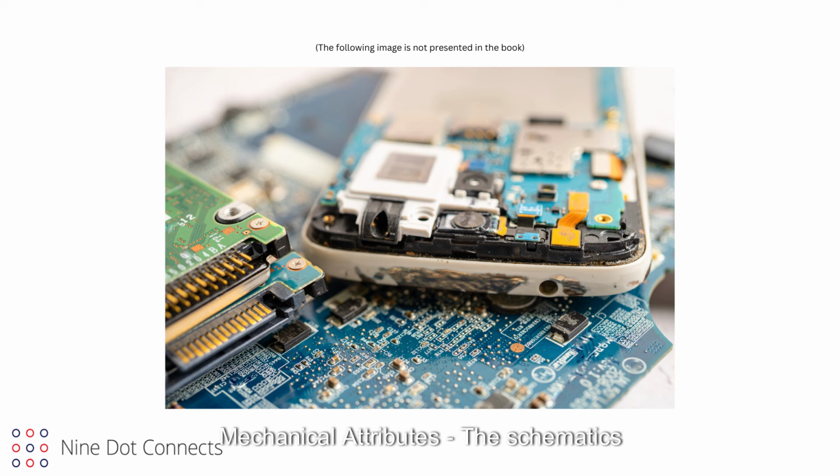Mechanical attributes. The schematics represent the conceptual aspect of the design, which does not consider the physical dimensions. Having physical dimensions provides these bounds. The mechanical dimensions may need to be changed as the design progresses, but it is far better to consider this up front, than to find out later that the circuit will not fit within the physical space provided.